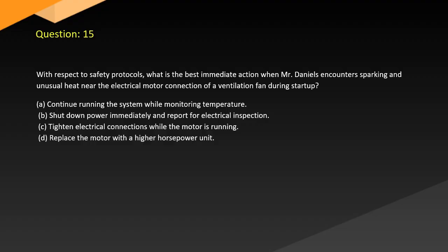Question 15. With respect to safety protocols, what is the best immediate action when Mr. Daniels encounters sparking and unusual heat near the electrical motor connection of a ventilation fan during startup? A. Continue running the system while monitoring temperature. B. Shut down power immediately and report for electrical inspection. C. Tighten electrical connections while the motor is running. D. Replace the motor with a higher horsepower unit.